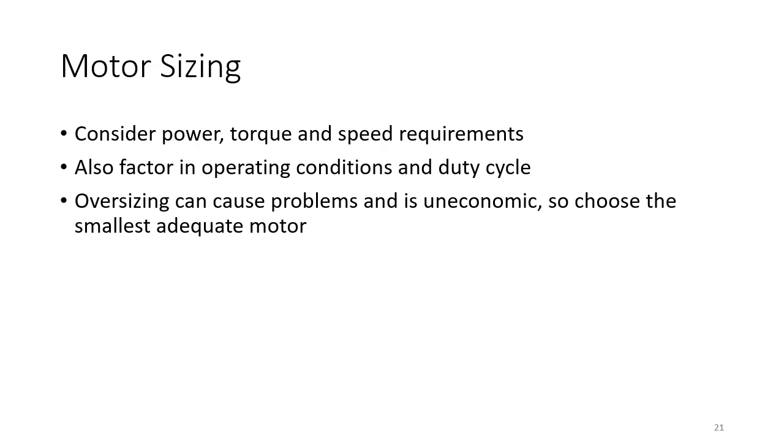You might also need to factor in other operating conditions and duty cycle. So do you need a motor that's sealed to IP67, or maybe a motor that's not quite so sealed and operates in more varying conditions? What about the duty cycle? Is the motor operating all day, every day? Maybe it's only operating on a shift basis. Maybe you're only operating it 8 hours a day, 5 days a week. Within that operation parameter, how often is the motor starting and stopping?